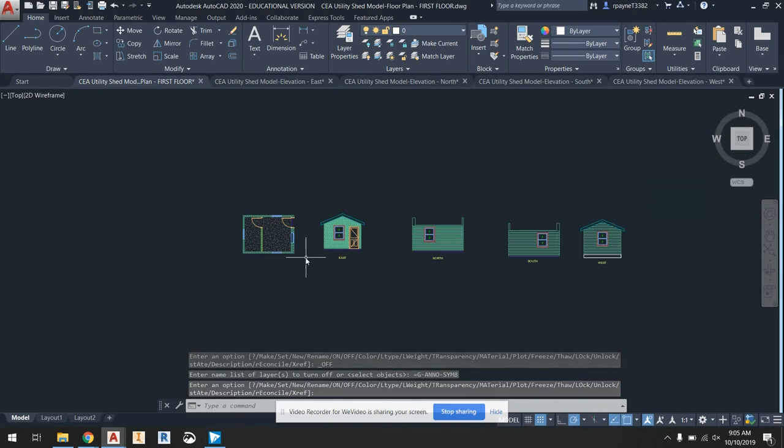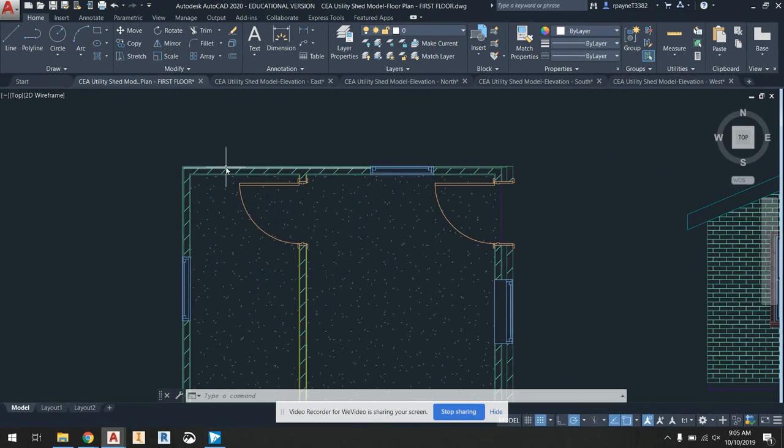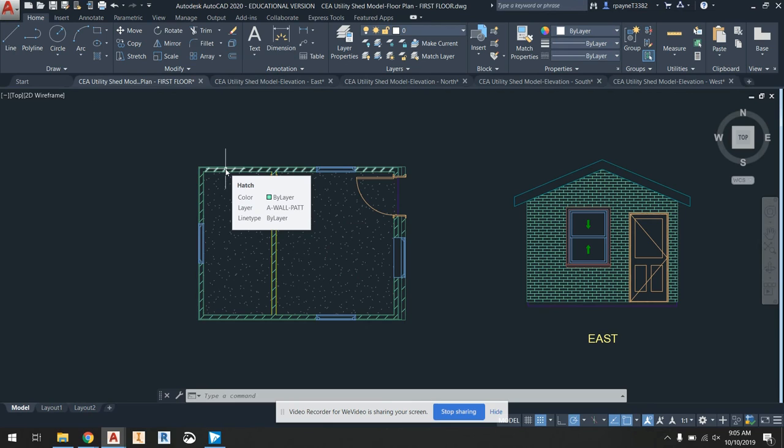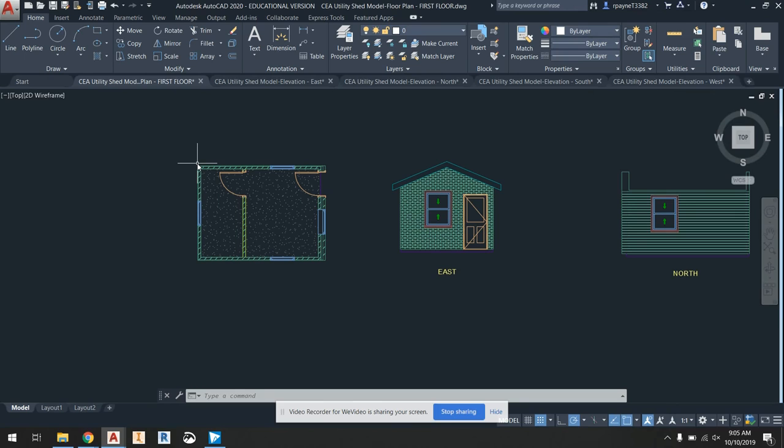Okay, good. So now, most of the stuff I want to engrave, meaning like kind of the laser will just burn the image into whatever material it is, whether it's foam or wood or whatever it is, as opposed to cutting when it cuts all the way through it. So burning, it's just the engraving. Technically, it's called raster. So when it rasters, it's like a light kind of burning, because that's what a laser is. It's just a very strong heat source. It's going to kind of just burn that image in. That's called raster. Vector, that's when it cuts all the way through. So the outline, the very, very outline, that's what I want to vector. The inside stuff I want all to be rastered.